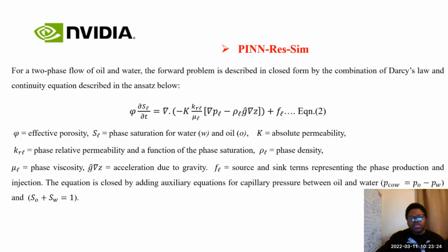If you assume there is no influence due to height, you're solving for the pressure. So the pressure is the same in X, Y, Z, in all directions. This is just pressure, but the permeability is a tensor, and normally the permeability in X and Y are the same, but the permeability in Z is like 0.1 of the permeability in X. F is your source and sink term given by the Peaceman well equation.